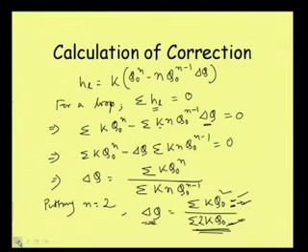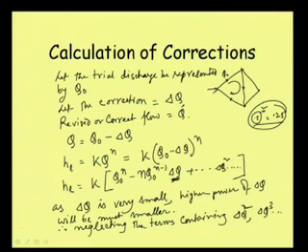Here we consider the correction such that the revised flow is the original flow minus the correction. So when the correction value is positive and the flow is clockwise, this value will have to be deducted to get the revised value.